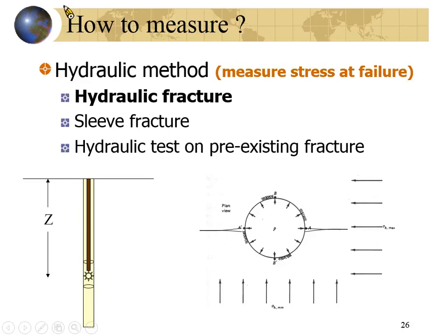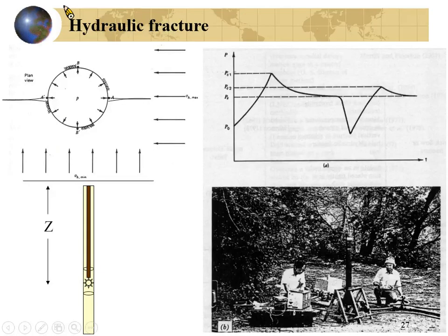Okay, we have sigma V and sigma H in two different directions. So we're trying to solve for the sigma H maxima and the sigma H minima, and the direction of the sigma H maxima and the sigma H minima. The procedure was something like this.